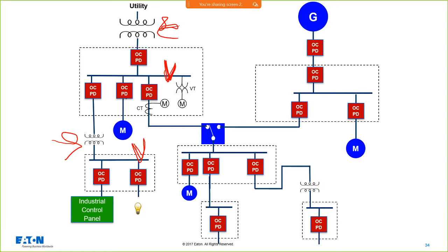So if you're designing a system, you've got to think about, what am I going to have in this power distribution system? For example, you may sit down and say, you know what, this is a heavy industrial. I'm going to have 4160 motors here. If I designed a system at 480 volts, I'm screwed. I need 4160 volts. I'm going to have to figure out how to make that happen. And my transformers are going to determine my system voltages to serve my loads.